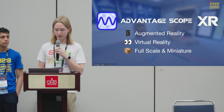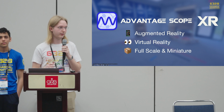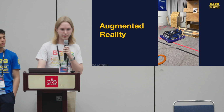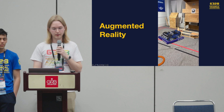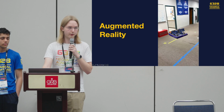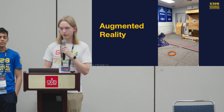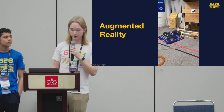So what does this actually look like? Well, we have some early prototypes to share, but keep in mind that all of this is very much still subject to change. Okay, so one of the first things that we tried once we got this running was to simulate an auto routine. So here, the robot and the game pieces are being overlain on our real practice field. So we can walk around and see this happening in 3D. We found that this was really great for getting a sense of scale and figuring out potential failure points of the autos.